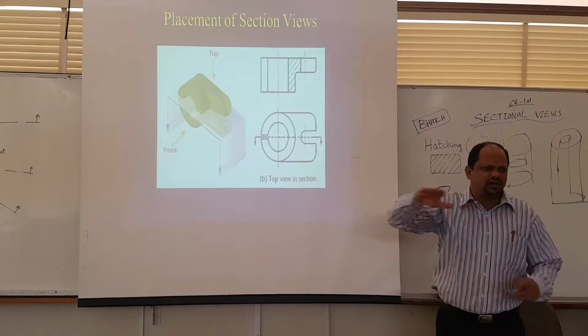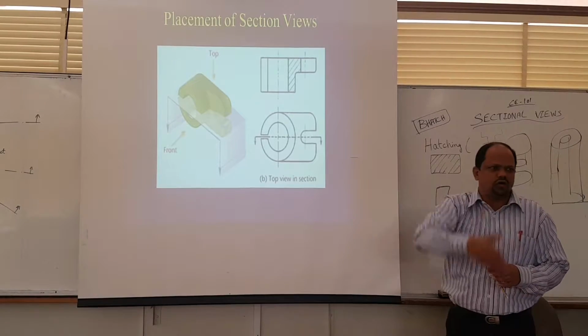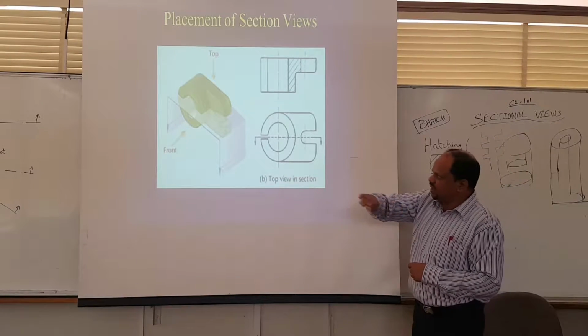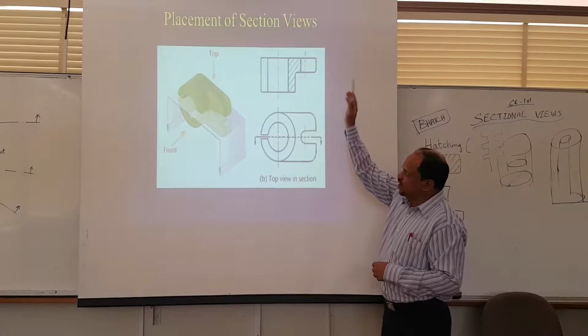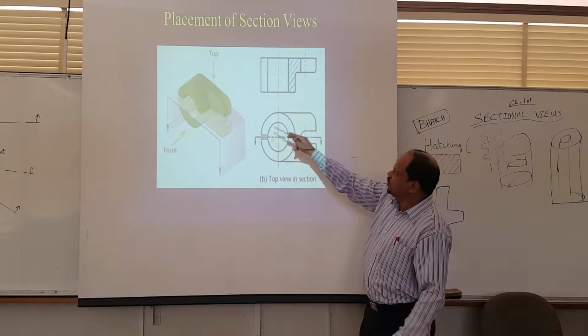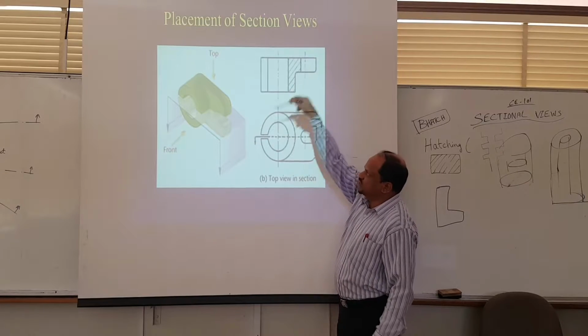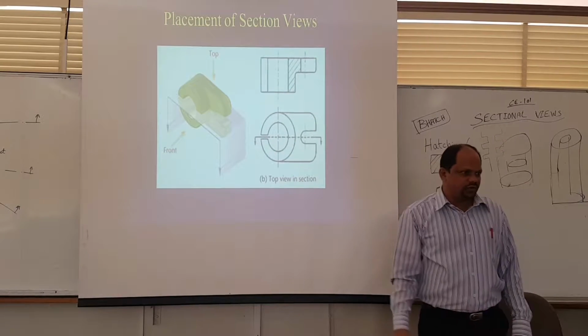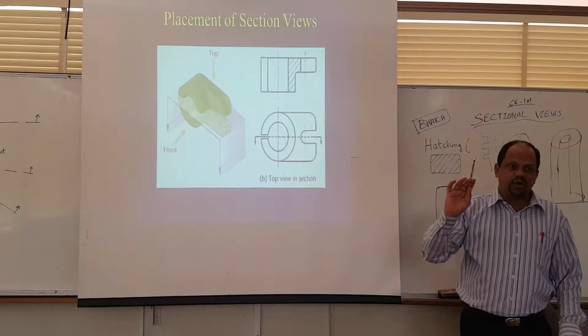It's just a cutter. Like you have a saw, you cut the object the way you like. When I am cutting like this, I am removing the upper part and viewing towards the down part, because there are two parts now. So we will hatch in the top view, because it is the top that you are seeing after cutting. Fine? So this is very important.